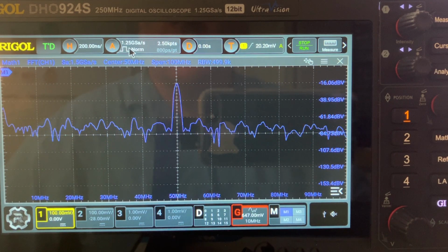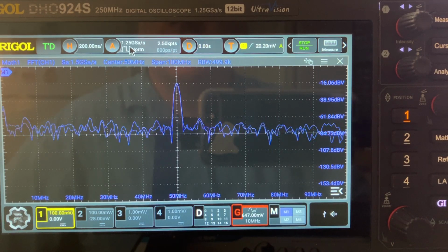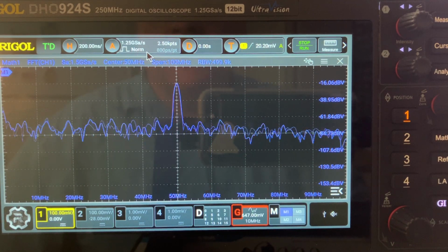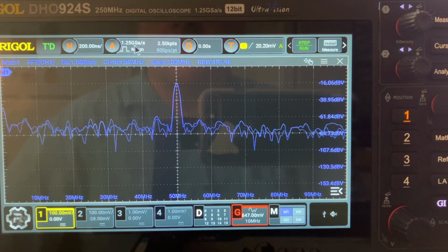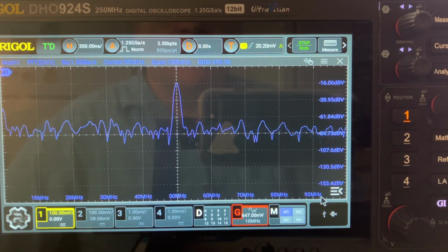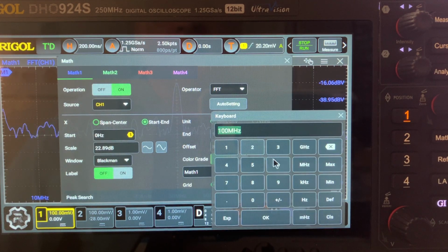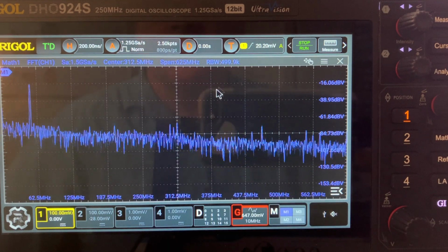The maximum frequency that the scope could give you is half of this, because of the sampling theory. You need to have 2 points per sine wave cycle, so the maximum calculated frequency is half of that. So let's try that. So maximum is 62.5 megahertz. You won't be able to achieve anything else.